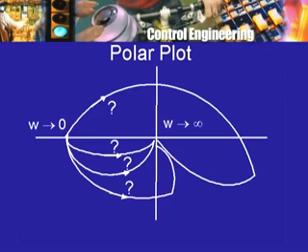All we know are the limiting values. So which one of these is likely to be the correct or close to the exact variation of gain and phase with frequency? This is something which we cannot immediately figure out by only using this approach, that is pole zero diagram, vectors drawn to the j omega point, angles made by those vectors, the lengths of those vectors, etc. This is something which we had already done in connection with the root locus method.